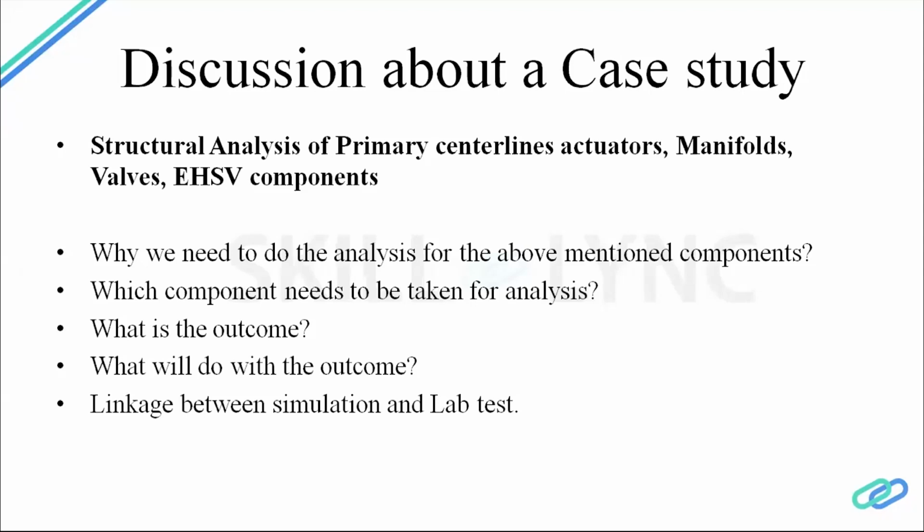Because for the lab test or qualification test, there is no alternative. A physical test will be there in any case, and we need to match our simulation result to that one with some percentages or some factors we need to add: material factors, notch factors, geometrical factors. We need to add many factors and come up with a very close relation to actual testing.